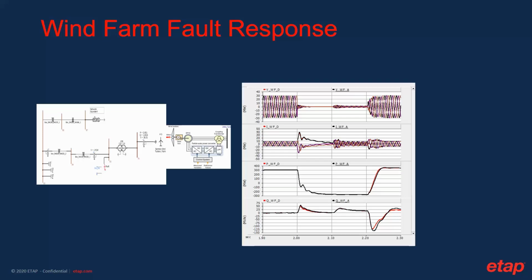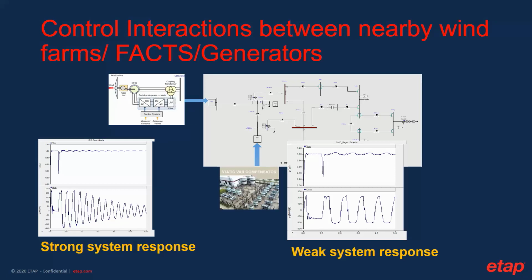And in those situations, what you want to know as an engineer is, what is the minimum rating of a synchronous condenser or a STATCOM that I can get away with and solve this problem, because the rating of the STATCOM will determine the cost of your solution. So I will show you a number of examples related to a wind farm study. One thing also to keep in mind, that I mentioned before: when you have 2 or more power electronic based devices or fast reactive power control devices in a weak local area, those devices can interact in an unstable manner.